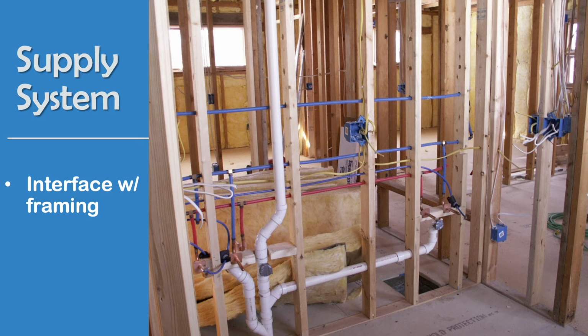And then it's either going to go across our ceilings in attic spaces or in our floors, between floors, or if it is a basement or a slab on grade. Remember, all the plumbing has to be in place before that slab is poured, and if any renovation needs to happen, replacement or changing the location, that means you have to trench the slab to dig up the supply or waste line to move them.